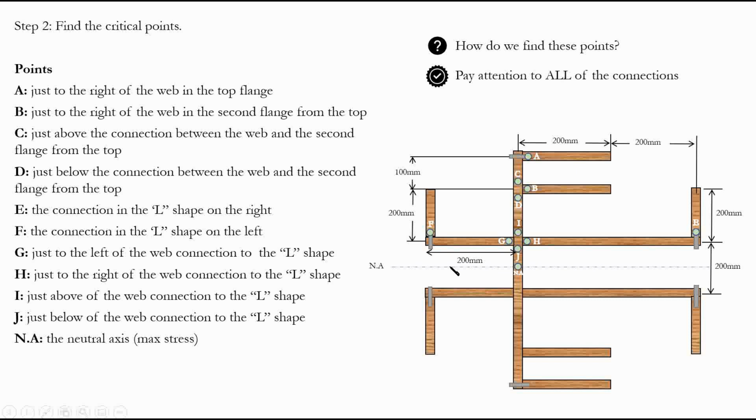And again, our force is basically divided into shear and flexure in our assumption in elastic beam theory, and of course, when you have maximum shear, you will have 0 in moment and 0 in flexural stress, and when you have maximum flexural stress, you will have 0 shear, which is what you see at the edges, right?